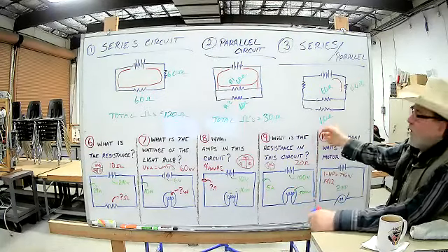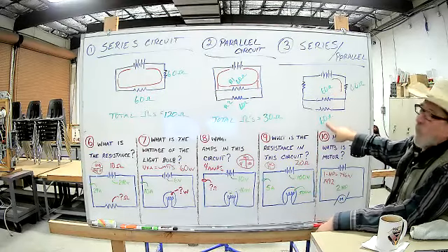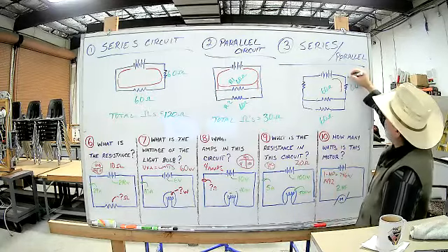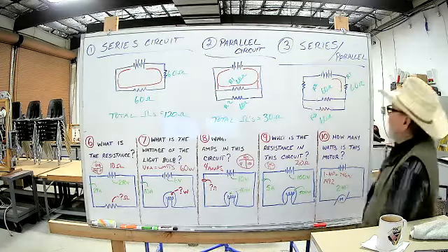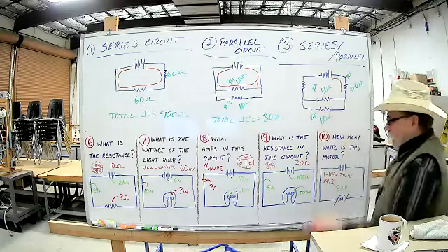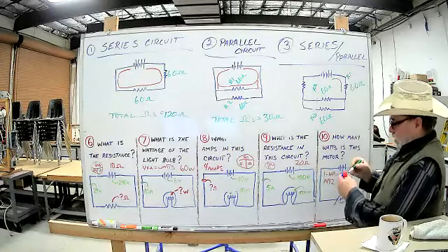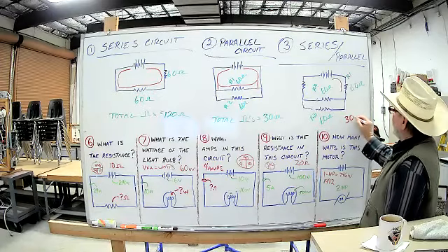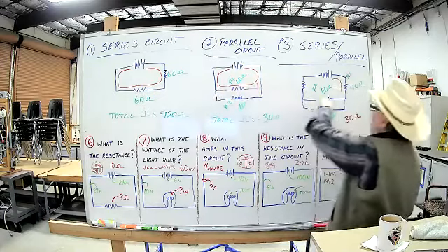So we're going to look at this. We already know that two resistors in parallel is going to be half of one of them when the value of the resistors is the same. Let's say this is R1, R2, R3, and we're going to look at R2 and R3. We got 60 and 60. They're the same amount, and we know they're in parallel, so we automatically know that's going to equal 30 ohms, right? This part is the same as just this part.